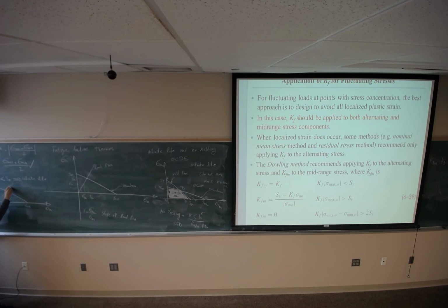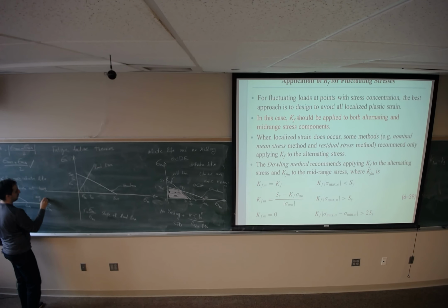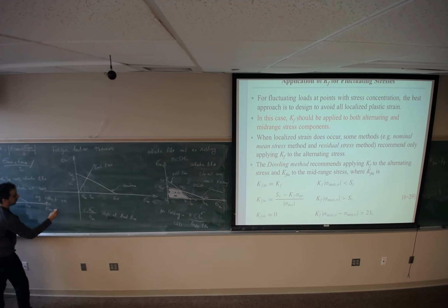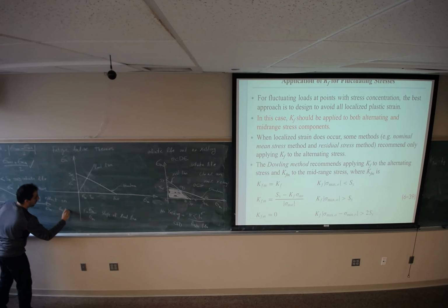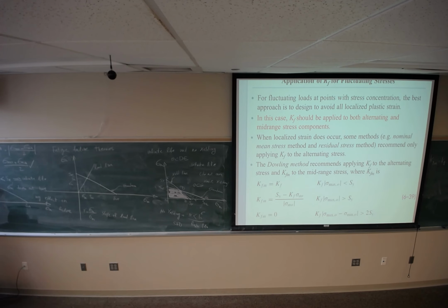Sigma M doesn't have any effect. So here, sigma M can be this amount, but as long as sigma A is less than SE, you should be safe. Meaning sigma M doesn't have any effect on failure.